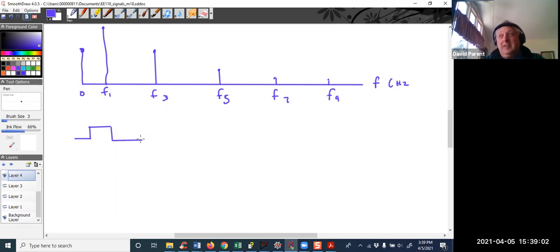except you must have seen that whenever you measure anything, things are bouncing up and down slightly due to noise. And sometimes they bounce up and down wildly due to noise as you walk near it, open the door, turn the lights on. You know, just because we have R, L, and C passive components in a compact model, meaning there's no dimension to it, right? All of these devices come from Maxwell's equations, and Maxwell's equations are always on, if you will.